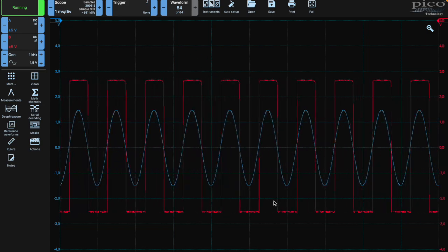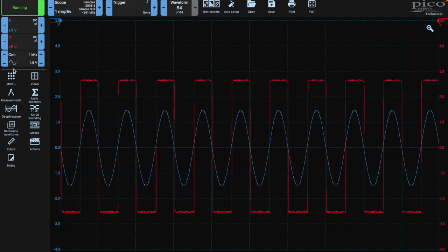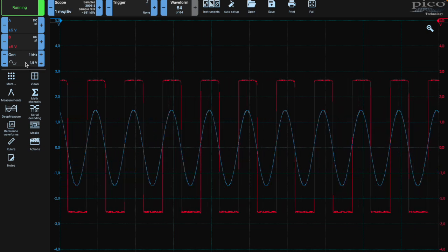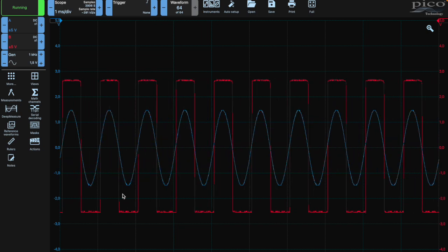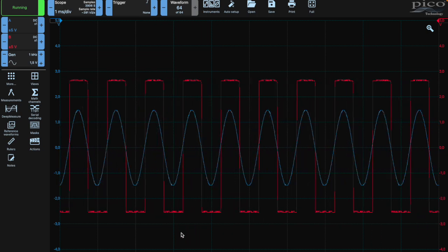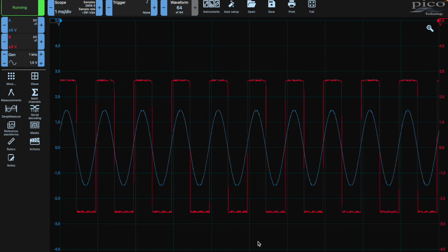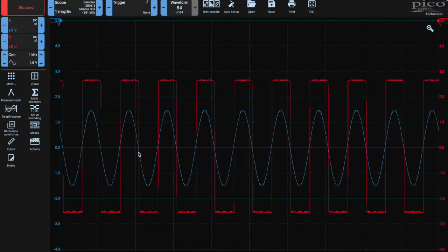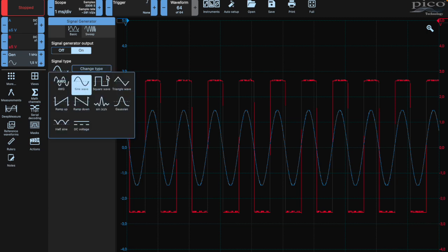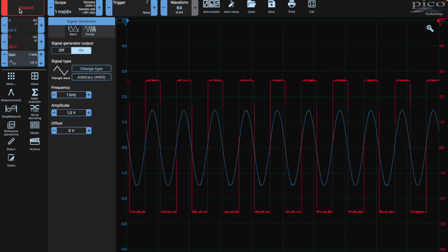So here is the picoscope readings. As you can see, similar to the simulation, we have the sinusoidal input wave, which does not quite reach 2 volts due to interference from all the parts on the negative 5 volt generator and the operational amplifier itself. We can see that the smooth signals peak higher than the sinusoidal wave, as it is dependent on the supply voltage of 5 volts, which is higher than the amplitude of 2 volts. We can also observe that the frequency of the output equals that of the input wave. Otherwise, we can observe that the picoscope measurements match that of our simulation, which is always excellent.